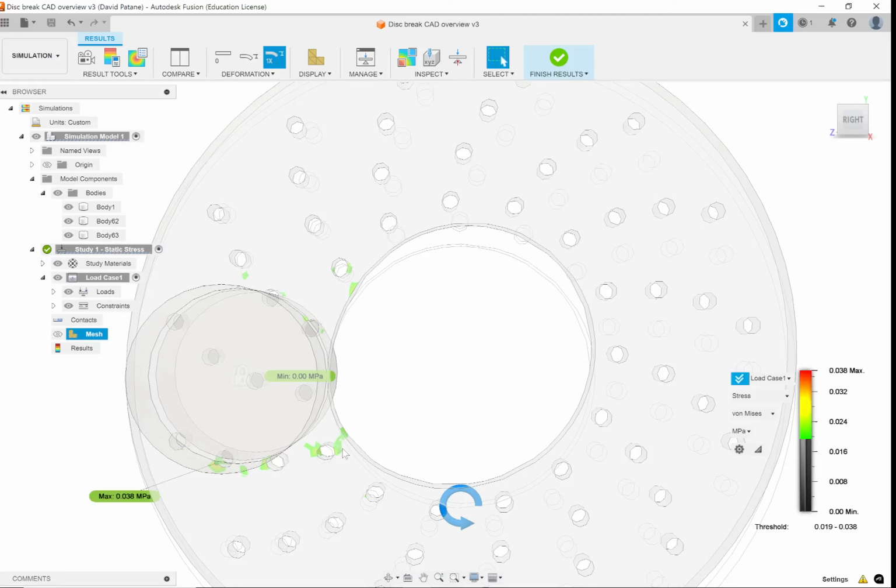It allows you to do finite element analysis, which can then do things like find out where the most stress on the object is. One thing I haven't shown you, but you can do many things with FEA. I'll probably do another lesson showing more examples of FEA. You can do things like see how the vibrations happen. You've seen in music or in science, you have tuning forks where you shake them and they make a particular sound. That's called a resonance frequency. And you can find out the resonance frequency of your objects, which means you can then find out where they're likely to break.